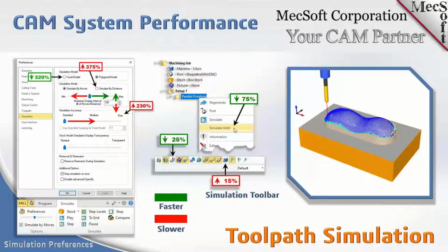And the voxel is inherently limited to the Z-axis of your toolpath. So as long as you're using just one Z-axis setup, the tool axis pointing only in one direction, which most 3-axis toolpaths are, then you can use the voxel model. It's much, much faster and uses a much smaller footprint than the polygonal model. I hope that helps.